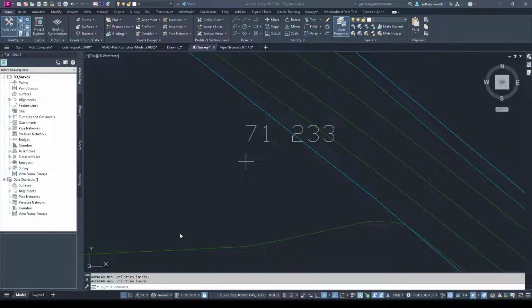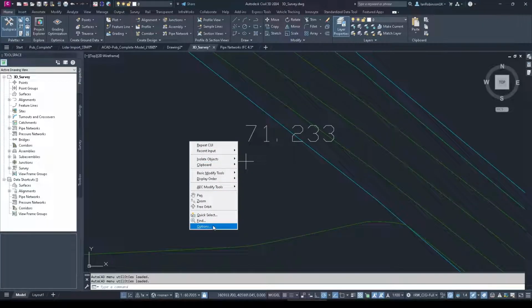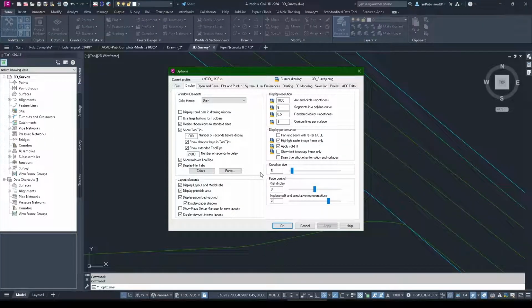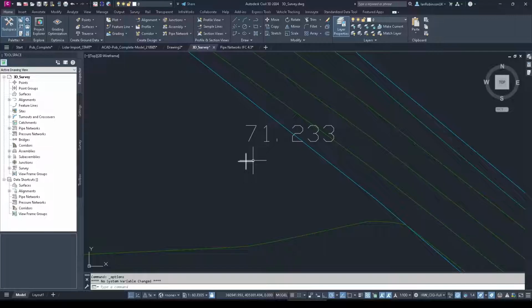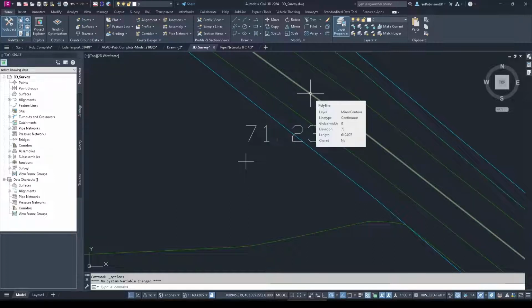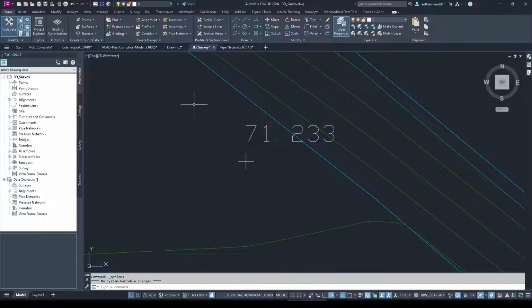Next thing on your software is back in the options. When you hover over an object in AutoCAD, I'll turn it back on here and let's hover some objects. Can you see it highlights them? Every time you hover an object, it highlights it. So you're asking your computer to know where it is, turn a tooltip on, and then highlight an object, which could be a very large object, or it could be a block that's very complex. So I think that is not much use either.